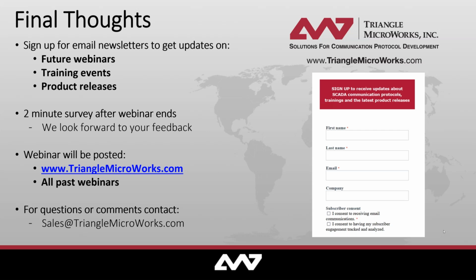So when I want to transmit any of the information from those devices up to my SCADA system, any of the devices up at the top at the SCADA level, they're going to be clients. And fundamentally what it means is that they're capable of subscribing to reports, that MMS or client server information that we spoke about.